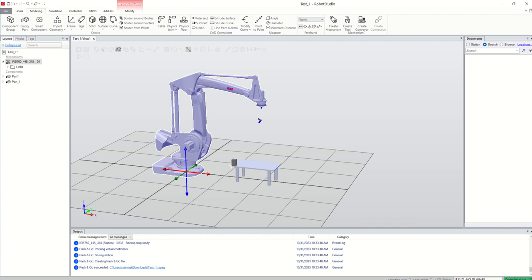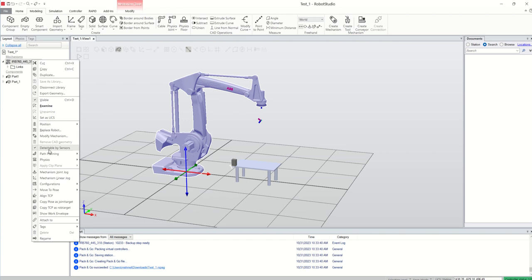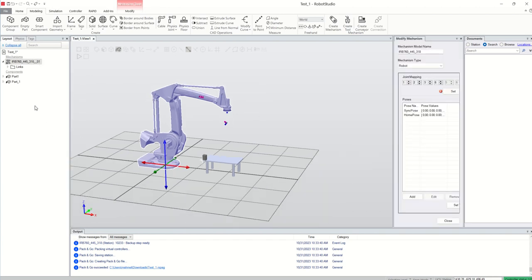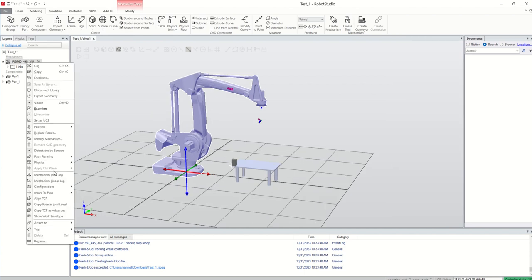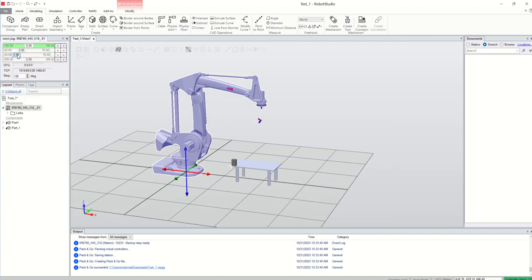And yes, here you have total, sorry, 4 axes, right? And how did you get that number of axes? Again, if I go there and do the modify mechanism, then basically not this one, sorry, modify jog. I think I did it before, right? Jog joint. Then you will see there are only 4 axes here: 1, 2, 3, 4.